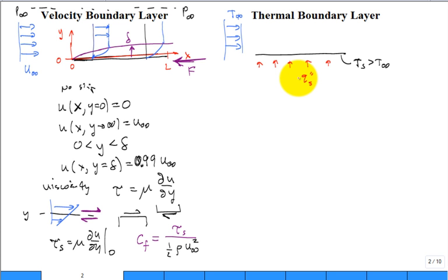It's convecting the energy, the heat transfer through that layer of fluid away. Okay. So force was the idea for the velocity boundary layer. Heat flux is the key idea in the thermal boundary layer. But just like this, if we have a hot surface, we can sketch the temperature profile. Maybe I'll sketch it at this location a little bit away from the leading edge, and then further away from the leading edge, getting toward the trailing edge. And I want to sketch, just like we did right here, temperature as the length of the line in the horizontal direction. That gives us the magnitude, a visual image of the temperature. Just like this, magnitude was U infinity, the length of that line for the velocity profile.